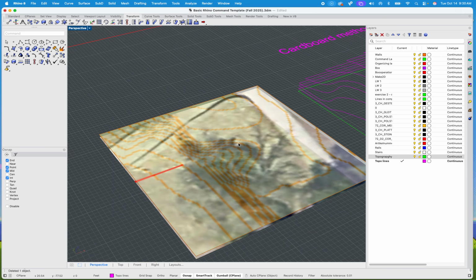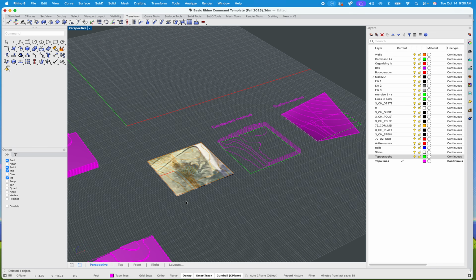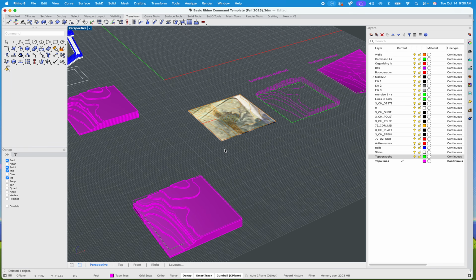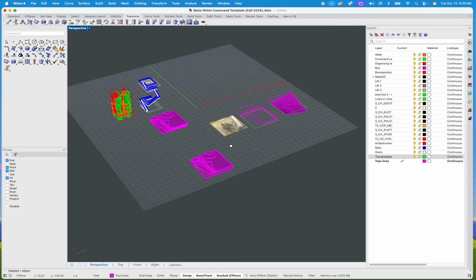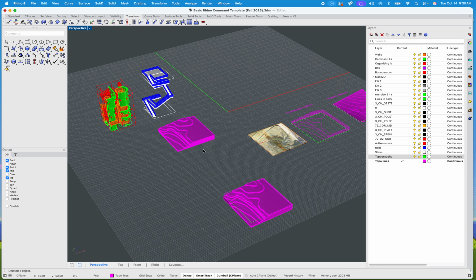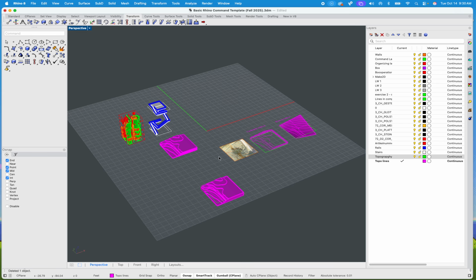We also went over a little bit of how to scale something, obviously through that measurement first, and learning that we make all models in the digital realm 1:1. I can't express that enough. I can't tell you how many times I have students go, "Sir, I accidentally made this 1/4 scale model," and I go, "I can't really help you because I don't know how accurate you made that model," right? Don't get me wrong, you may have made it 1/4 scale, but again, it will need to be scaled. Either way, we'll start here for part 2 next time.